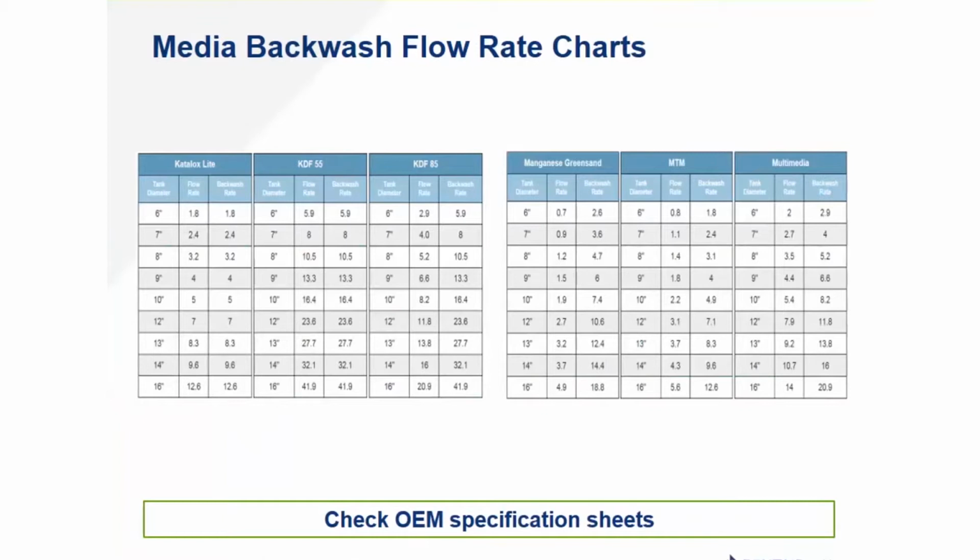I've literally seen neighborhoods where, house to house, street to street, well water quality is different depending on how far they went down, local geology and things like that. I've seen water come out of people's wells black and others perfectly clear, some with lots of iron, all in the same neighborhood. Question: Zeolite seems to solidify easier than birm, but as you said, it depends on water chemistry. Yeah, that really is going to depend upon water chemistry.